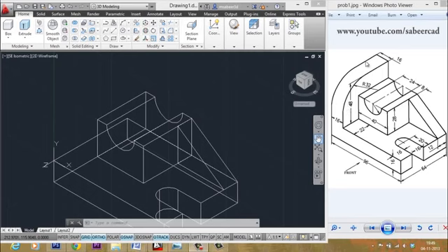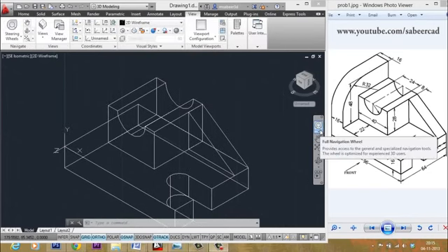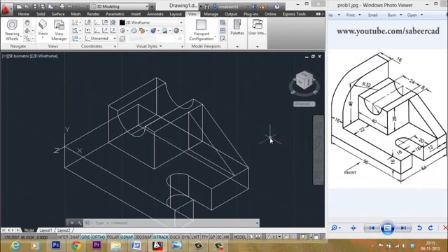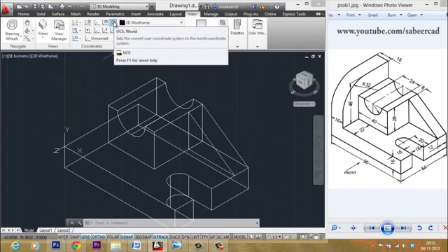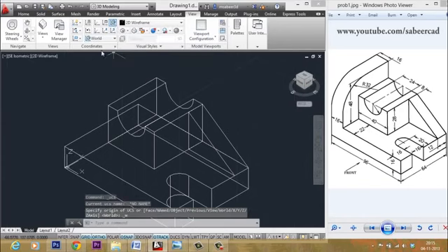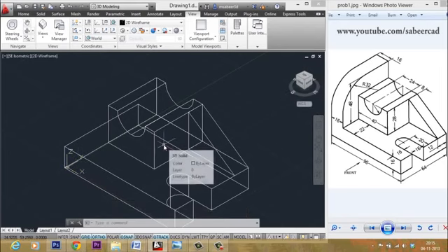But you know that if you want to make this part, you have to construct a profile on a different plane. In fact, that plane is the right plane. If you have any confusions in identifying the various faces of an object in AutoCAD 3D, I'll explain in just 1 minute. First of all, you just switch over to World Coordinate Setup. Just click on the WCS tool of the coordinate palette.